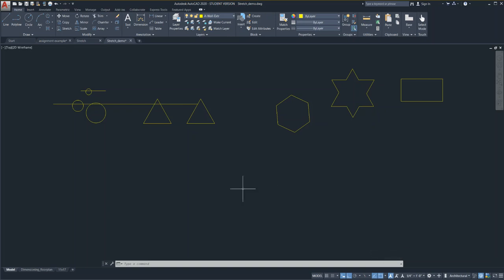Polylines, I'm hoping that you remember polylines. Polylines are pretty simple. They function just like lines. The one thing I did want to remind you about with polylines is the p-edit, which is to take a polyline or lines that have been separated or broken apart or created separately and join them together. Okay, so polyline, it functions just like a line.